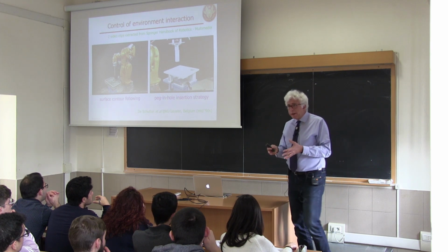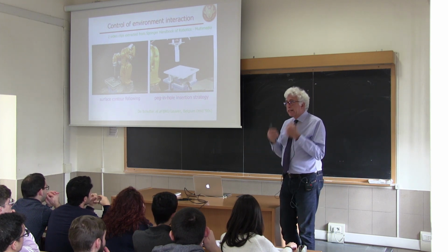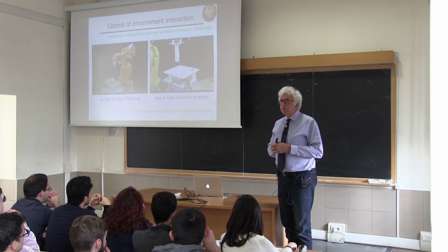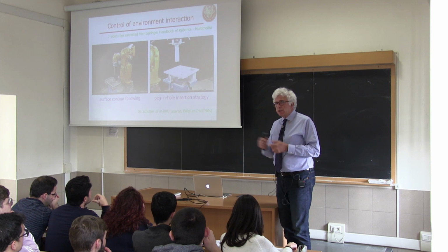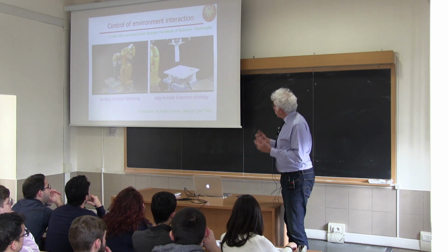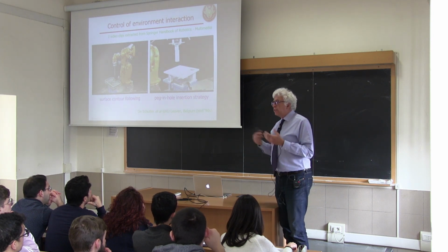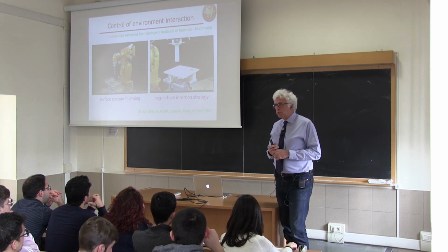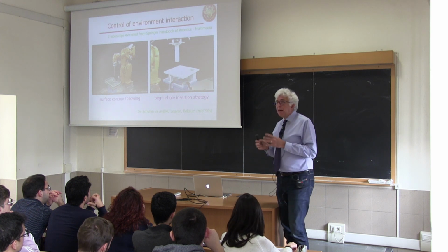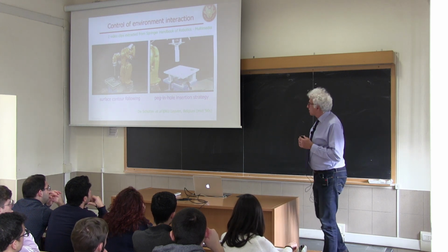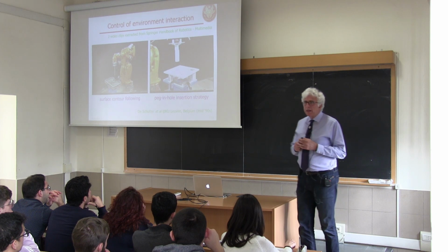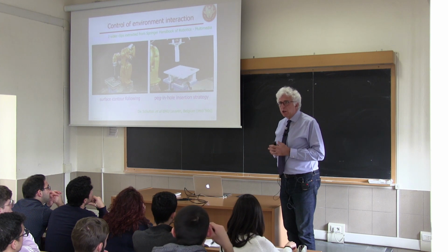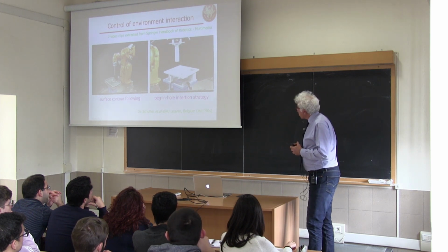So you may have a camera overlooking the object, and so you can extract the geometric information of where the end effector should move while applying forces. We already discussed this issue, and we mentioned that in general you need to have some dynamic model in order to understand how to control the joints of the robot. If you have a force torque sensor, you can slightly get rid of this, but we will see the full formulation in the hybrid force velocity control topic.